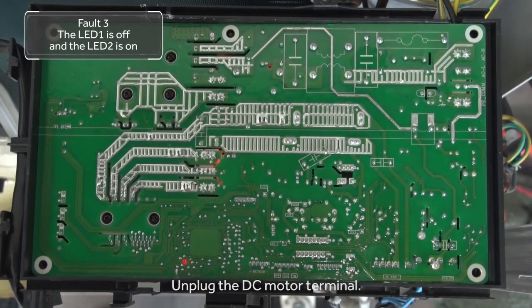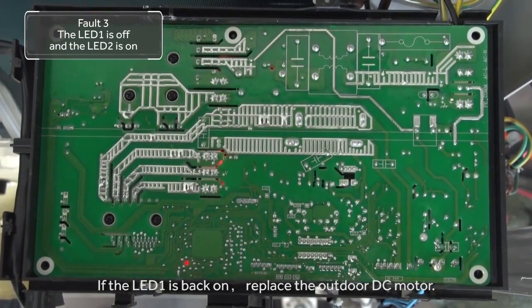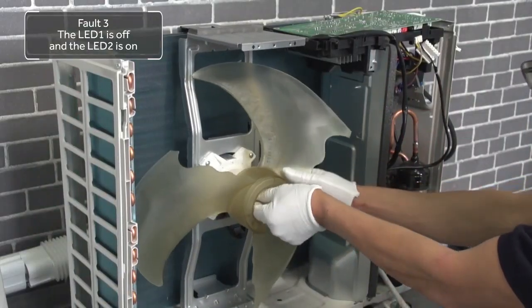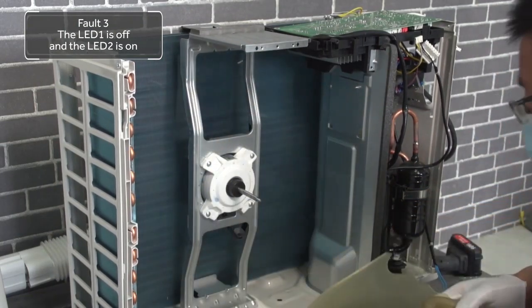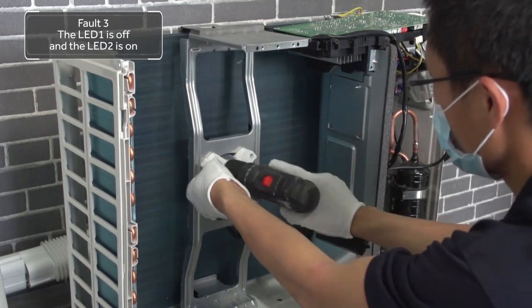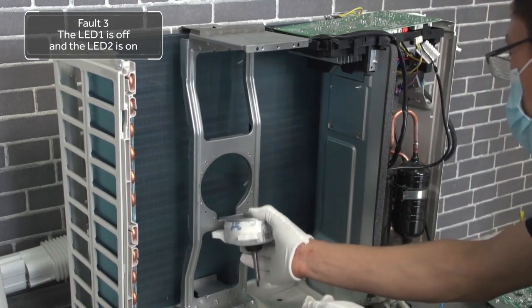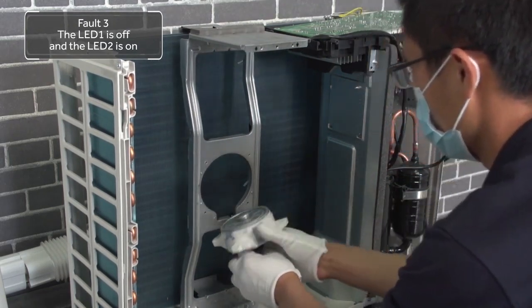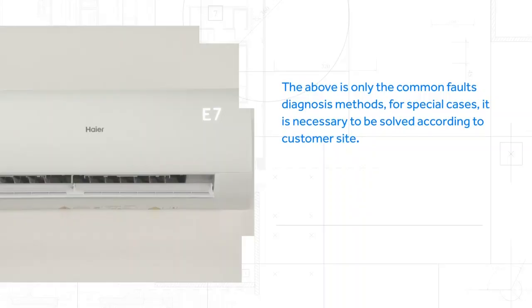Unplug the DC motor terminal. If the LED 1 is back on, replace the outdoor DC motor. The above is only the common faults diagnosis methods. For special cases, it is necessary to solve them according to the customer site.